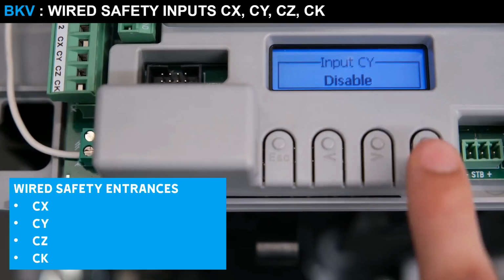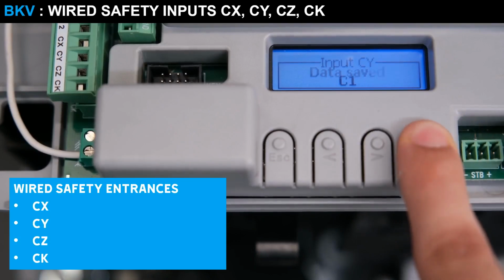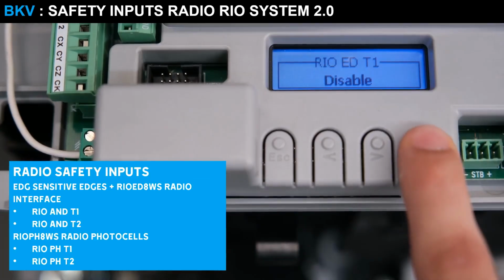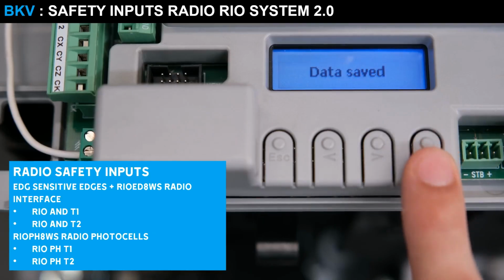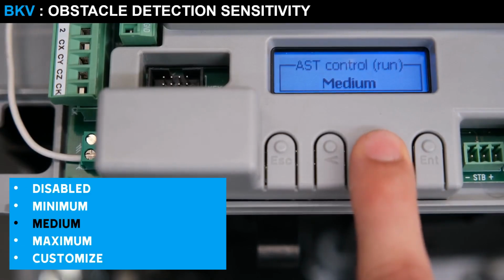Once the CX wire input is set, you move on to the next ones, CY, CZ and CK. In the presence of the Rio radio system, it will be possible to set radio safety devices such as sensitive edges and radio photocells. The AST function allows you to adjust the sensitivity of the automation to obstacle detection. It is recommended to initially set the average value.